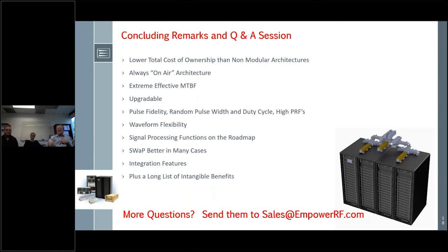How much noise can you operate with is really the... and I'm smiling about that question because it does come up. And yeah, Paolo, it's frequency, it's power. It's not an absolute answer. There is not an absolute answer. Okay, 8 kilowatts amplifiers air-cooled use about 8 fans, only on the RF portion, and a few fans that are less loud in the controller.